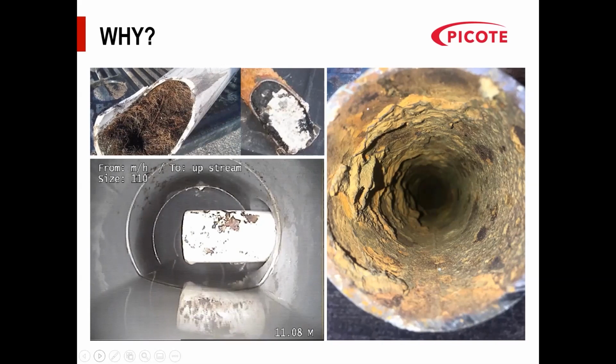as you look at your screen, that's an intruding 32mm waste pipe coming in from a kitchen into the main drainage pipe. So we get intruding connections. We'll also get a build-up of fats, oils and grease, but also the occasional reinforcement steel bar being knocked through, or fence post being knocked through the drain of the pipe.